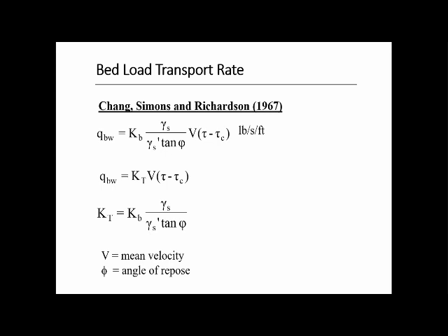So they developed what they call a semi-empirical formula, which is also based on shear stress. So this is the direct empirical formula that you can use to calculate the bed load transport, which equals KB times the submerged specific weight of the sediments,